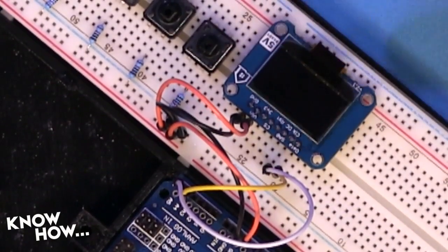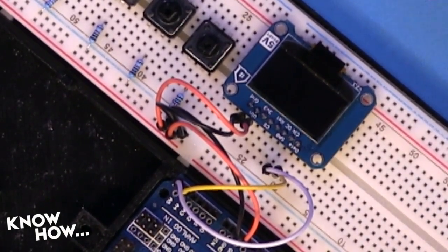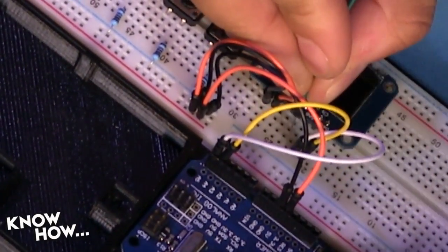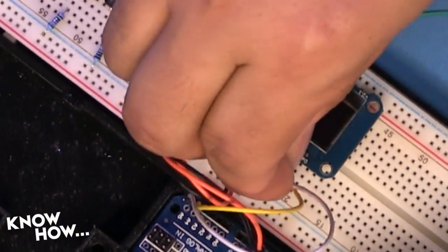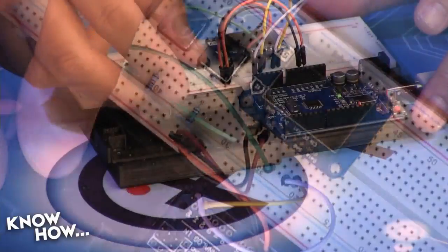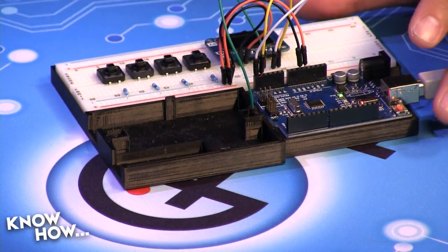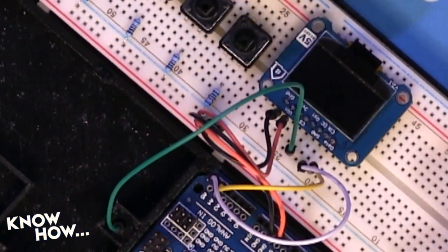There's reset. And reset is sort of a shortcut that the library that we're going to be using uses the reset pin to just say, go ahead and clear everything out. Yeah, in case something gets stuck. Right. So my reset pin is right there. Very good. And I'm just going to set this aside because we don't have a pin assignment for it just yet, not until we get into the code. Actually, put it right there. Ta-da! Okay. So this is going to give us our basic OLED connection.